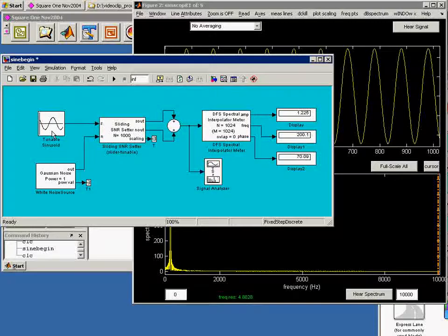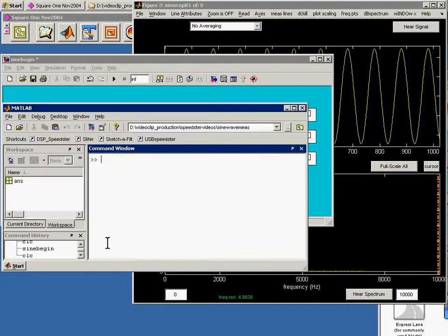Maybe a magic choice which would exactly fit in without all this randomness of phase. Well, I can do that. Suppose I wanted to have 10 oscillations taking place within that frame of 1024 points. Well, I happen to know that the sample frequency is 20 kilohertz, and you need that in this calculation.